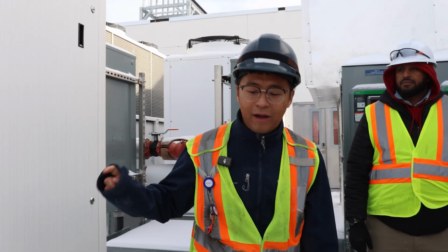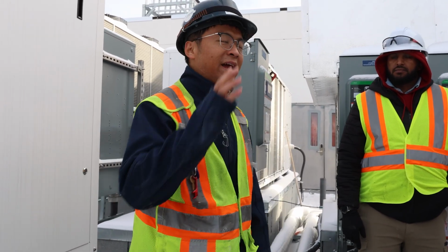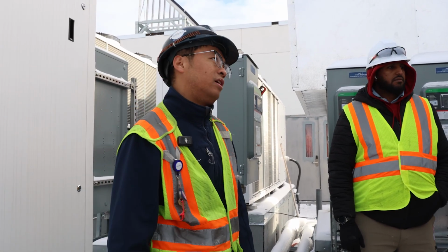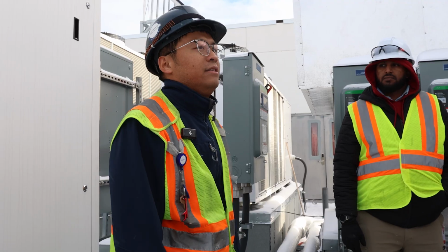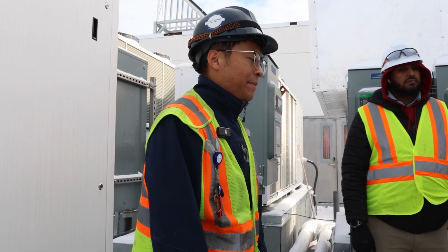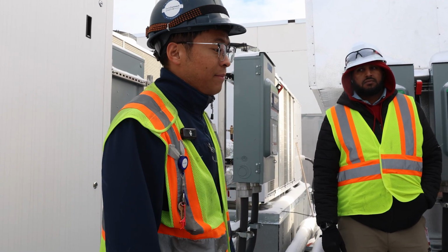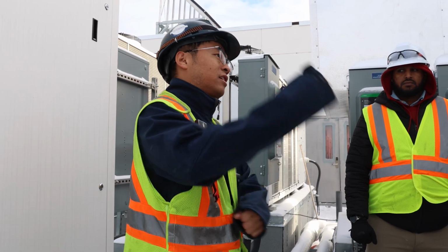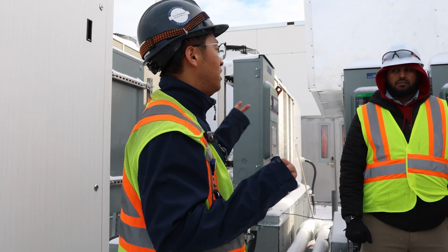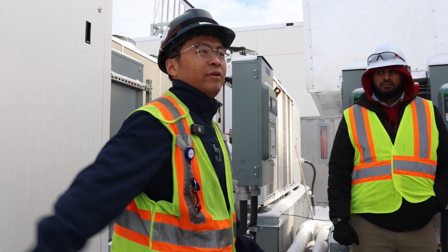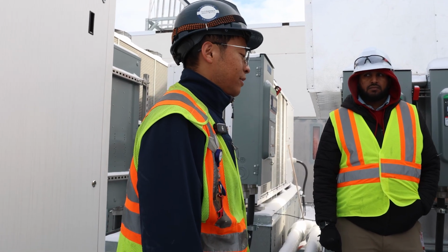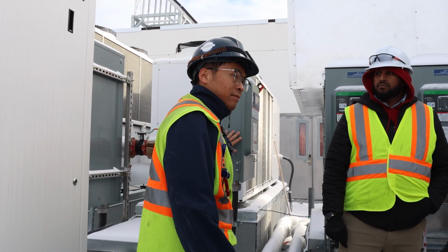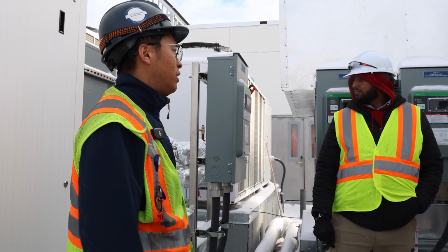As of now, air source heat pump 1A, 1B, 1C, 1D are being turned on and off together at the same time, doing the heating mode and cooling mode together. One set point, through the BMS. But for maintenance, we would recommend turning them off through the BMS, because it will start and close properly, since there is an isolation valve associated with those units. So it's better to turn them off through the BMS. And if you are actually doing the maintenance, make sure the disconnect is off as well.